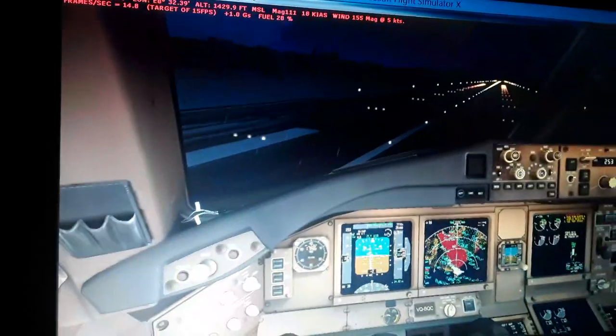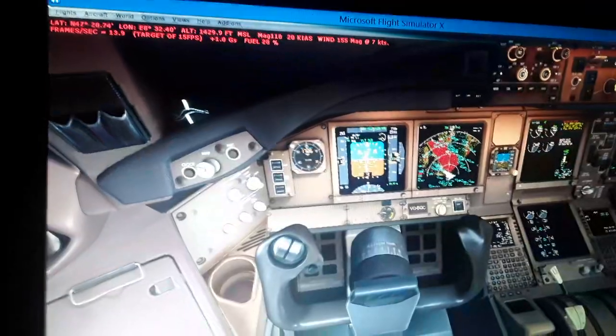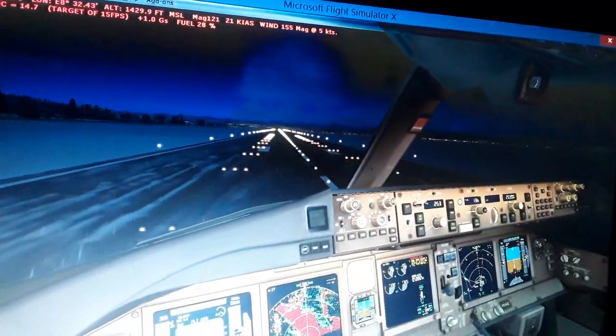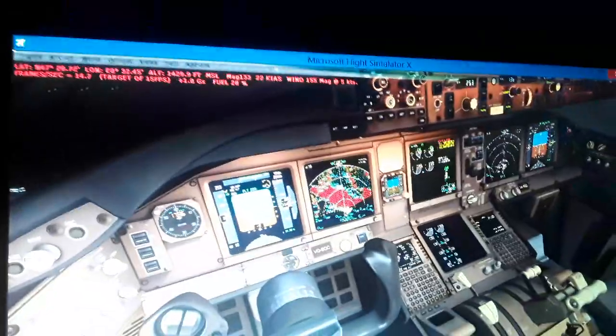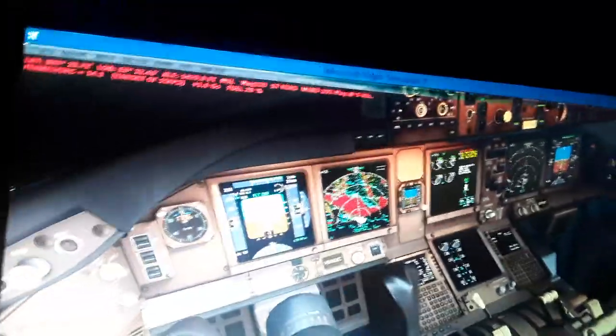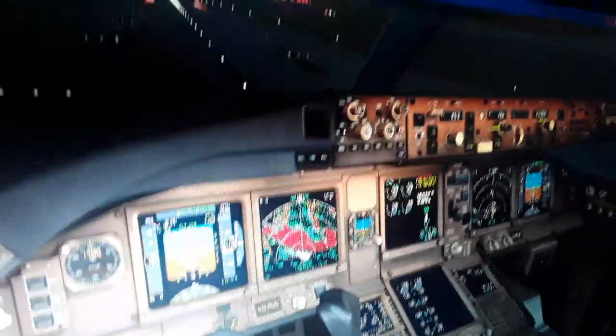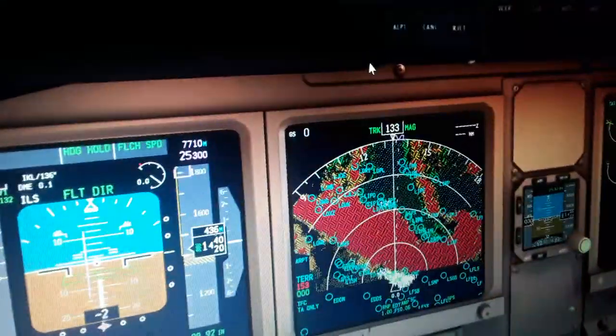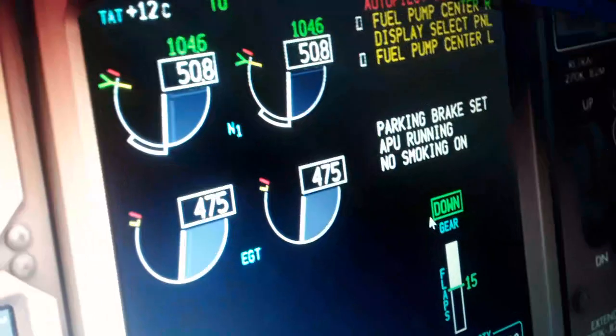We have the runways open, advance the thrust levers again, use the parking brakes again, align with the runway first, and we have the information we need inside the cockpit for takeoff and for flying. So everything is ready. We only need to set the range here, the LNAV, and we set the thrust levers forward. We will see the thrust increase for the takeoff.